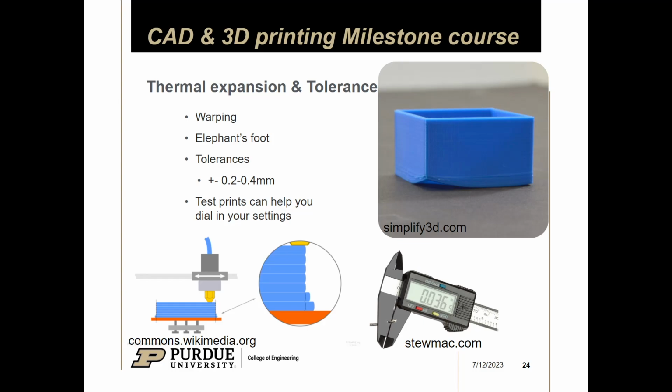A lot of the stronger materials require a very, very hot end. PETG prints at about 230 degrees Celsius. Stronger filaments will need to be 300 plus, and that's something most printers cannot do. I think the strongest you can get out of a print like this is polycarbonate. There are polycarbonate PETG blends, where they mix polycarbonate in with PETG to get a stronger filament, but they're generally more difficult to print with.